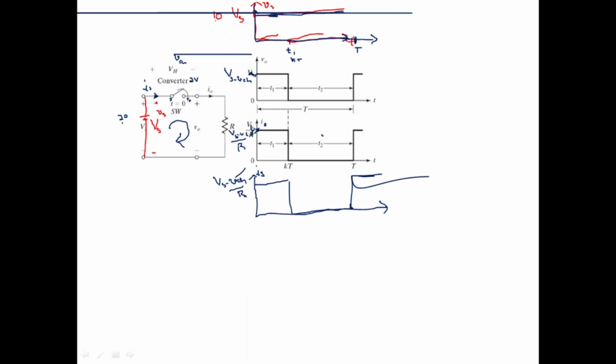So we should keep in mind, Vs is constant, its value is Vs, source voltage. Output voltage instantaneous values take a magnitude of Vs minus V chopper and 0. I naught, output current instantaneous, is Vs minus V chopper divided by R, and 0. Source current instantaneous is Vs minus V chopper divided by R. If V chopper is 0, then it becomes Vs, this is also Vs, this is Vs by R. This we should keep in our minds.